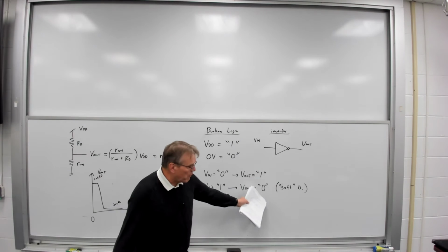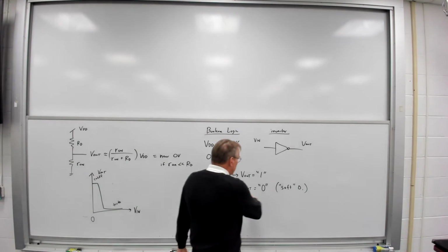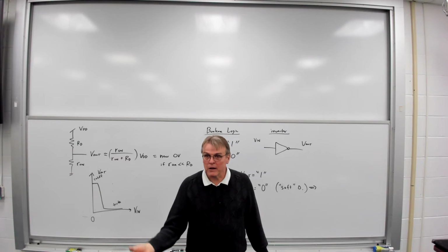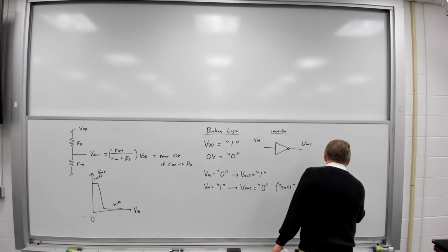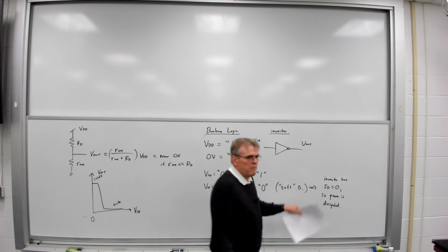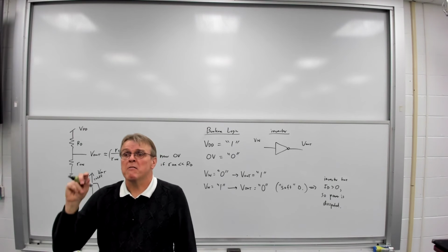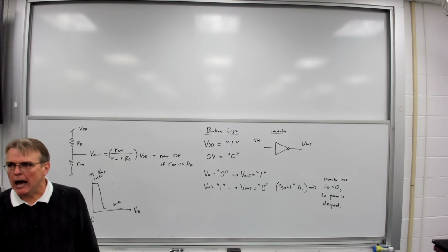First of all, it's not what we call a hard logic 0. It's a soft logic 0. It's not quite at 0 volts. Also, during this soft logic 0, current is flowing through the circuit. ID is greater than 0, and it's dissipating power. Now you'll say, well, what's the big deal, Professor Holman? Yeah, I mean, so you're dissipating a little bit of power. Well, the big deal is I don't have one of these in a circuit. I have millions of those in a circuit. And if half of them approximately are dissipating power, that chip is going to be glowing red hot.